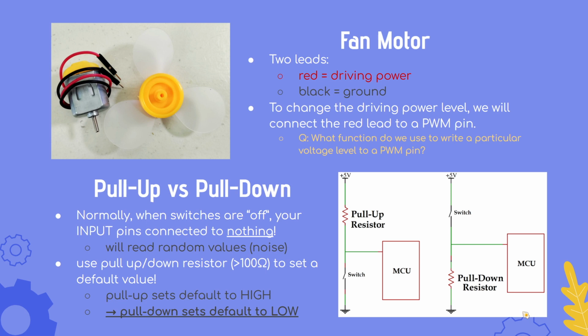Let's say you have a hose, and you spray really hard on the ground, it might damage the rocks and move them, right? You don't want that to happen. You want to limit it so that it kind of trickles over, right? So that's how you prevent it. It's not really a short to ground, but in a way you're preventing an error that could happen, because circuits in the real world all have variability and errors, and your component can just get totally trashed. But basically for pull up, it sets it to high, so that's your default.